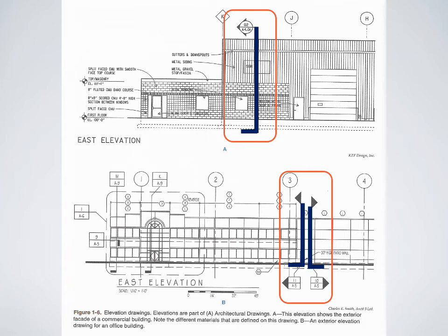So let's take a look back at that elevation drawing again. Those marks I've made are highlighting lines with arrows and letters and numbers. There's a lot of information from these otherwise random assortment. Each of those dark blue lines indicate where the section cut is being made, and the arrows indicate which way the drawing is looking towards. And those numbers and letters will tell you which page to find that section drawing on. This is a quick lesson on how understanding the layout and language of construction drawings helps you understand more details about the drawings and how to navigate through an entire set of plans.